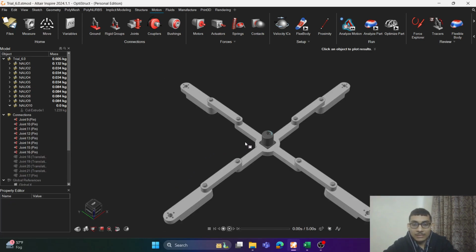The retracting drone arm mechanism is basically a slider crank mechanism having the crank, the forearm crank mount here, the connecting rod, and the slider. There will be a propeller on the slider while there will be a motor on the crank, and this motor will cause the rotation, and there will be an inward and outward movement of the slider, which will vary the distance between the propeller and the center of the drone.